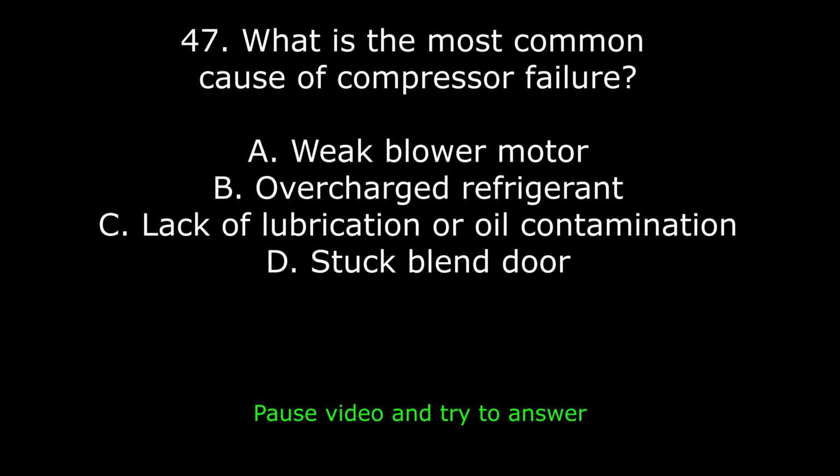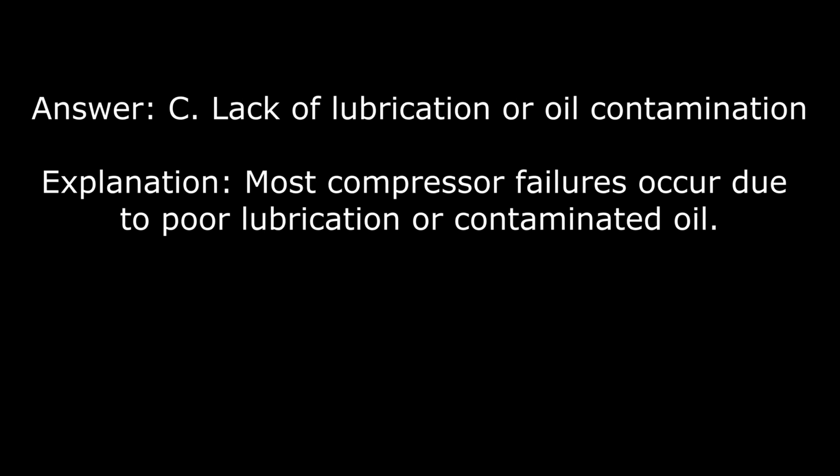47. What is the most common cause of compressor failure? A. Weak blower motor. B. Overcharged refrigerant. C. Lack of lubrication or oil contamination. Or D. Stuck blend door. Answer: C, lack of lubrication or oil contamination. Explanation: most compressor failures occur due to poor lubrication or contaminated oil.